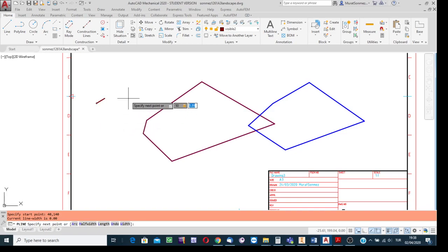Yes, you see AutoCAD understood that it is a different case, so it took the arc simulation from the screen. AutoCAD understood that the first number which I input is the delta x value. And then write the delta y value. If you're going to create the line as upwardly inclined, delta y is positive. If the line is to be created downwardly inclined, delta y must be written as negative. It is important. Using relative coordinates, don't forget to consider the direction.